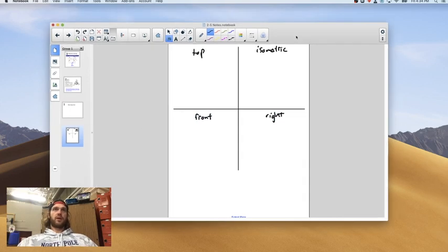All right, super. So you can take Legos. I would recommend between 6 and 10 Legos. Make sure you use the big blocky ones, not the really flat ones, and make some sort of a construction. And then don't make it too terribly complicated, but complicated enough that it's interesting to draw isometrically. Okay, and you're going to do a multi-view sketch on a piece of paper. So I'd recommend taking your piece of paper, dividing it evenly into 4 equally sized segments, and that's where you are going to draw.